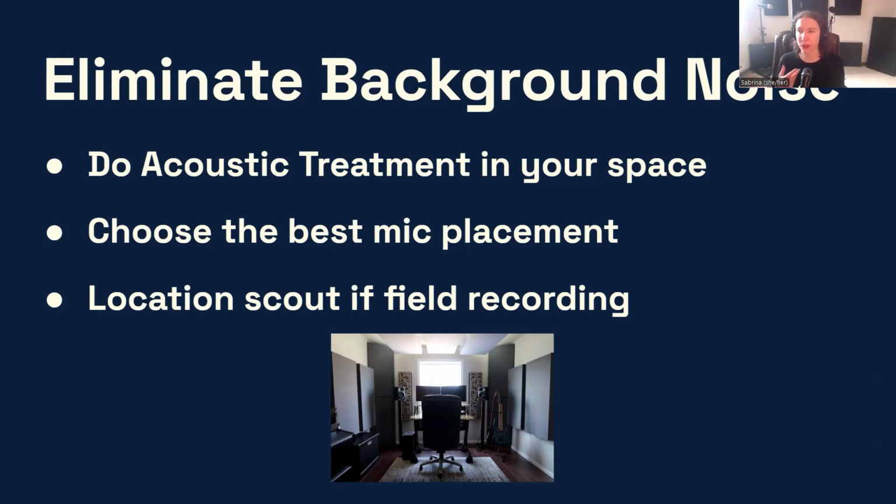So if you have a directional microphone like this cardioid one, or ones we'll talk about later, where you choose to put the mic really matters. It really matters for what you're recording, but also what background noise you're picking up. So if you know your fridge is the biggest offender, make sure if it's a cardioid mic like this, that you're going away from the fridge with your mic, not towards.